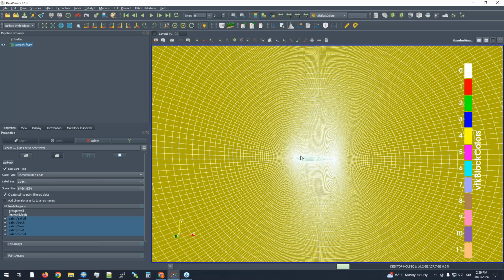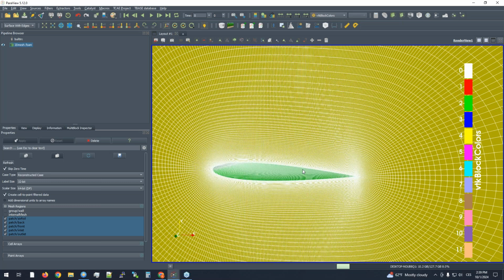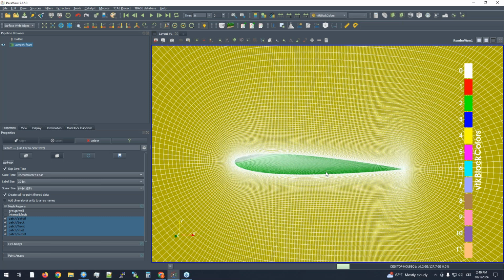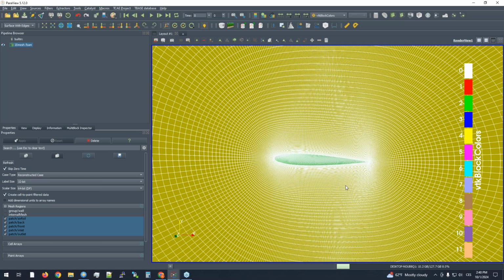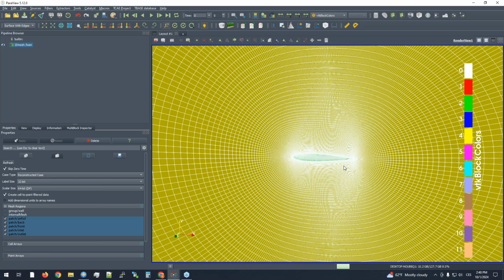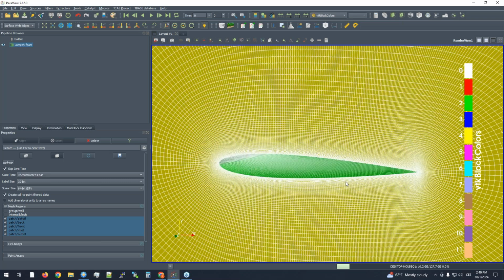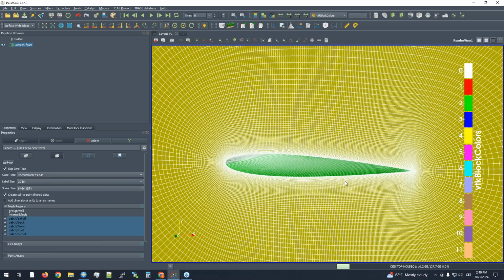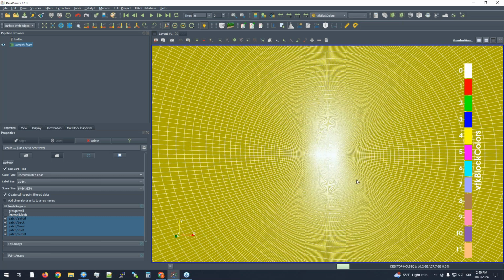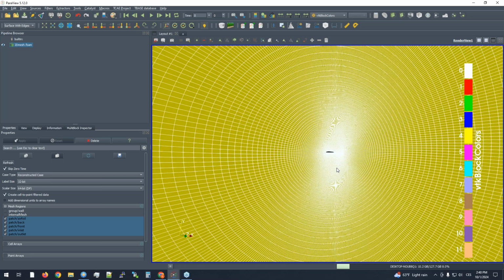computing demanding, but for example, to fully study all aspects of the turbulence and so on, you need to go to the 3D. So the 2D cases in a turbulence model is some kind of pseudo simulation, because the real flow has 3D properties, not 2D.